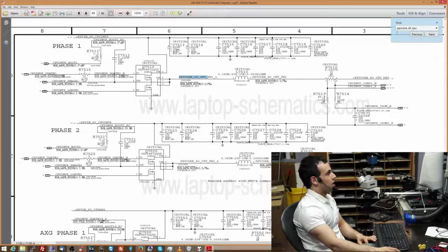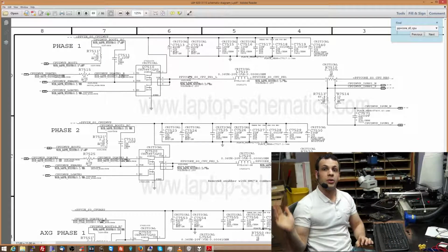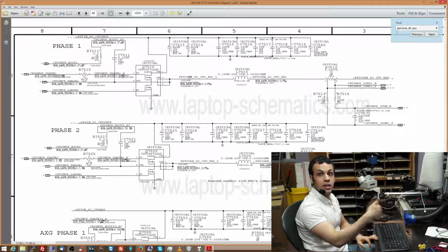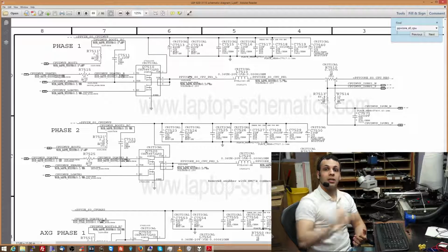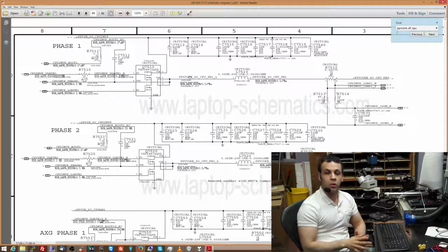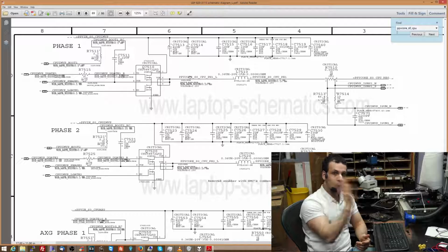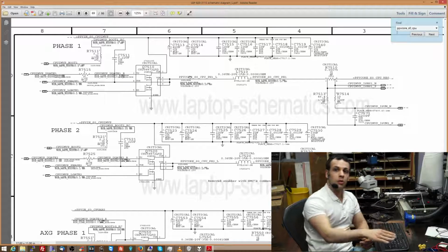So you have that 12 volts, and what it's doing is opening and closing it. So that gate and that gate signal are going to open it and then close it, open it and then close it. So you have a spike of 12 volts and then 0, a spike of 12 volts and then 0. And what that does is it creates a voltage that averages out to 1 volt that the inductor and the capacitor can then turn into a flat line. So we can use transistors to turn high power supplies into low power supplies, a higher 12 volt power supply into a lower 1 volt power supply. That's one way that a transistor is very helpful. So by turning into a wire, 0 ohm, and then an infinite ohm resistor, wire, infinite ohm resistor, we get 12 volts, 0, 12 volts, 0.